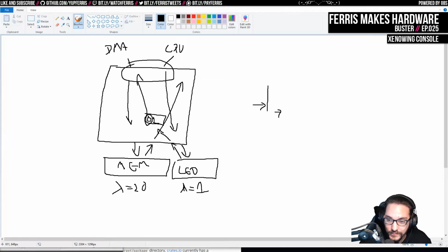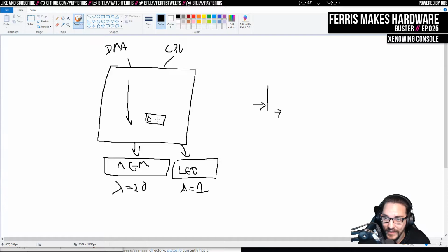And this can be solved if everything has the same latency and you serialize all the reads through this bus, then you're fine. But it's this variable latency that kind of kills you. And all of that is really a product of the fact that we're interfacing with DDR memory, where we don't have any control over that latency. So the way that I'm thinking about solving this is similar to how we have this read return FIFO here. I still want to have that.